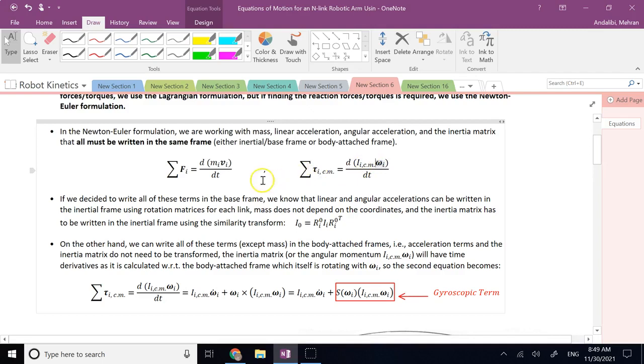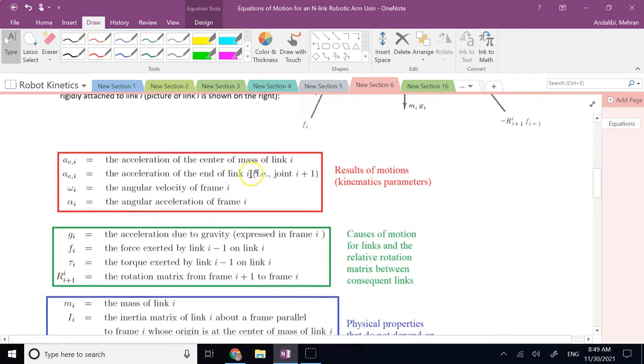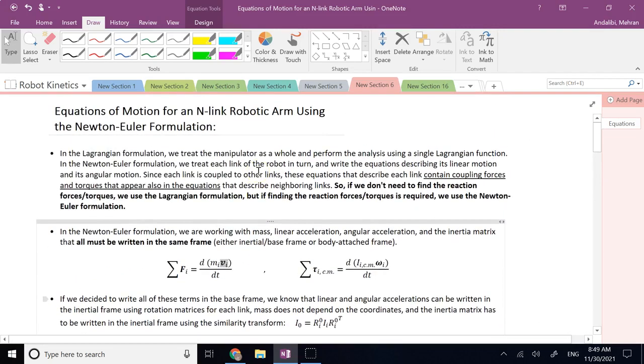So, how can I write linear and angular velocities for each rigid body in the base frame? Well, that's not a big problem. We learn about Jacobians, and we learn that V and omega can be written in terms of Jacobians, or you can directly use the kinematics formulas of rigid bodies, which is equivalent to that, correct? So if you remember from rigid bodies,